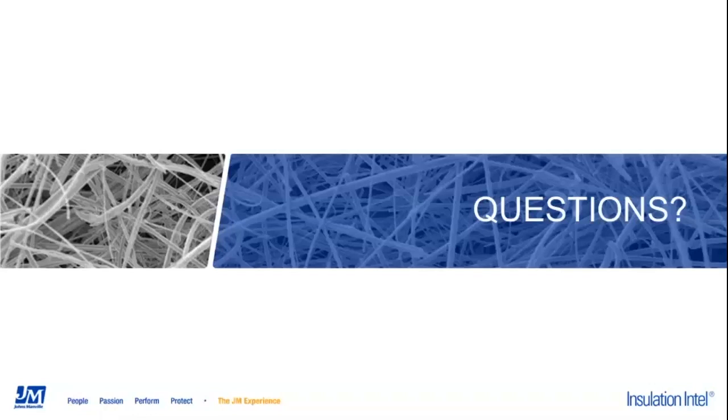Excellent. The next question is, how safe is mineral wool? Mineral wool is safe to manufacture and use when, as we say, certain common sense precautions are taken to avoid temporary mechanical irritation, like long sleeve shirt, long pants, gloves, and some eye protection. Just like glass wool fibers, the mineral wool fibers are sufficiently biosoluble that they do not persist in the lung long enough to present any kind of cancer hazard by inhalation.